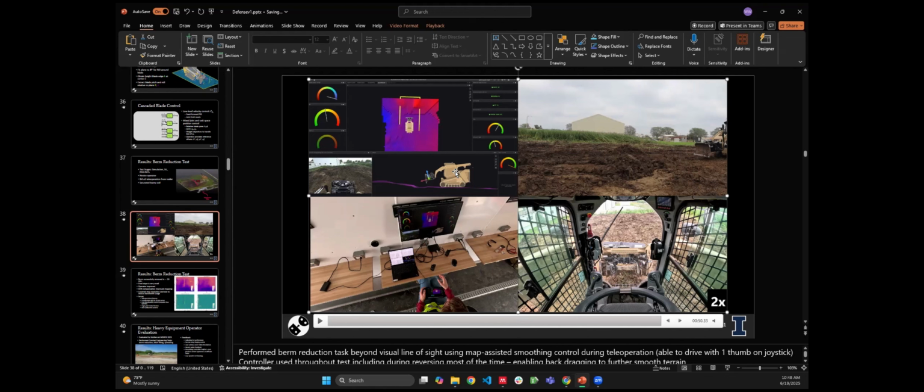It does a little bit of work. I think the diagnostic computer right now actually interfaces with the onboard vehicle J1939 port to get some of the information on the RPM and that kind of thing, feedback on the vehicle. But yeah, that's basically all it's used for right now. It's kind of planned for future operations.